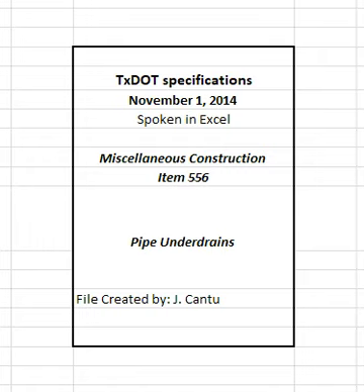Table 2. % retained on sieve, Tex 401A. See table in specifications. Loss by decantation as determined by Tex 406A must not exceed 1% of the material retained on a number 4 sieve or 4% of the material passing a number 4 sieve. Use Type B or Type C filter material around the underdrains unless otherwise shown on the plans. Do not place Type A or Type D filter material within 6 inches of perforations.